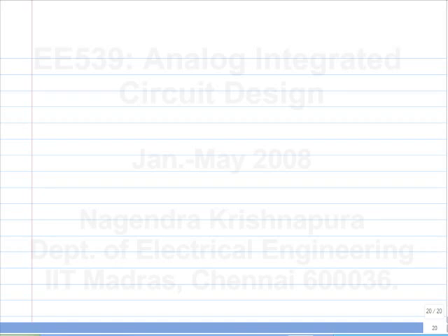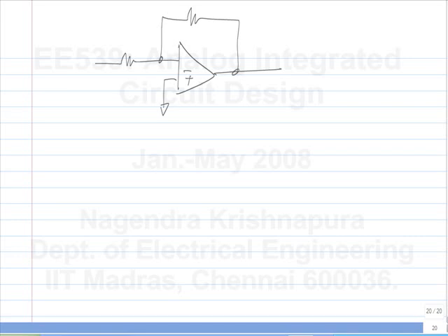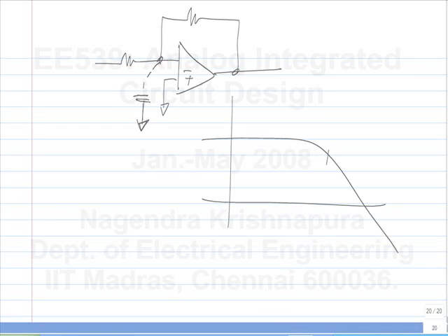So this is quite an important circuit in that area, as well as it's representative of another circuit which is used even more widely perhaps. So this is an inverting voltage amplifier. So what happens? You will have a parasitic capacitance from this. What do you think the effect of this is going to be? So let's say I design it for this particular bandwidth. So will I see something like this?